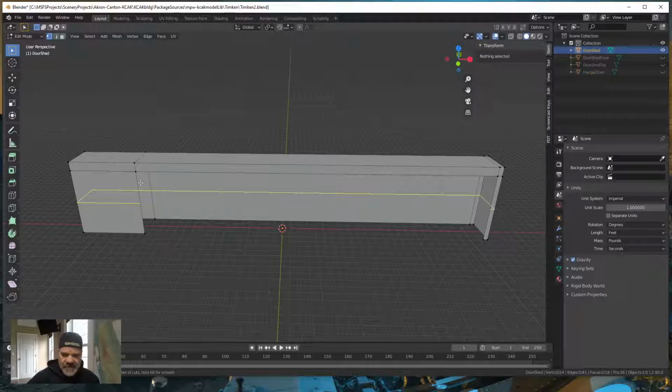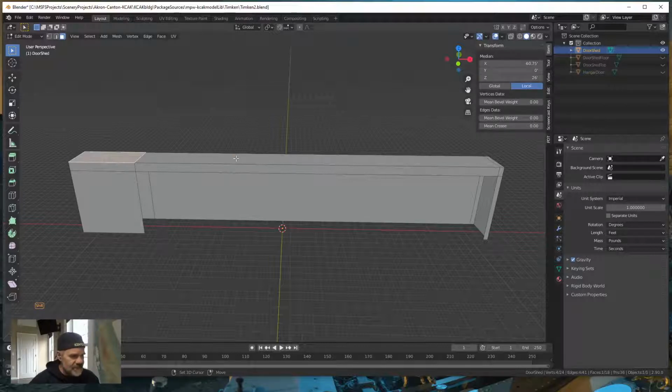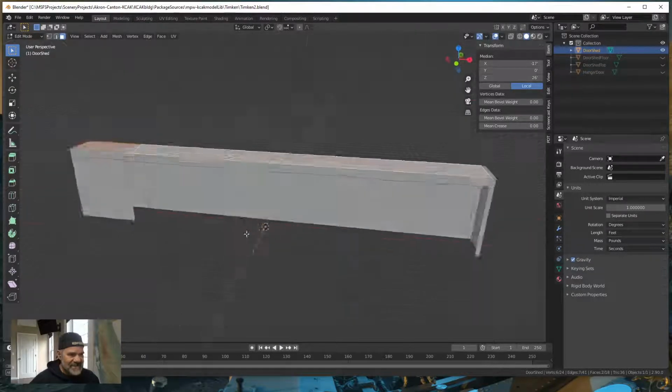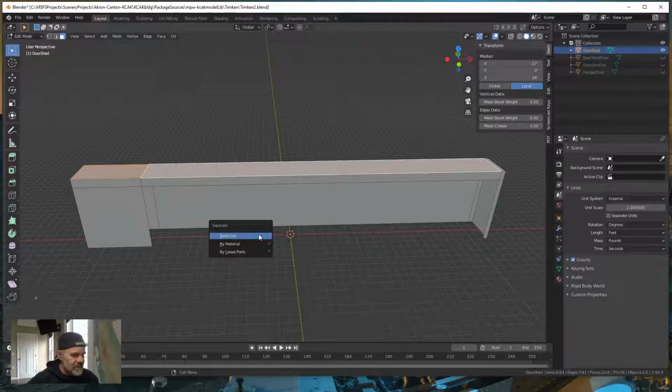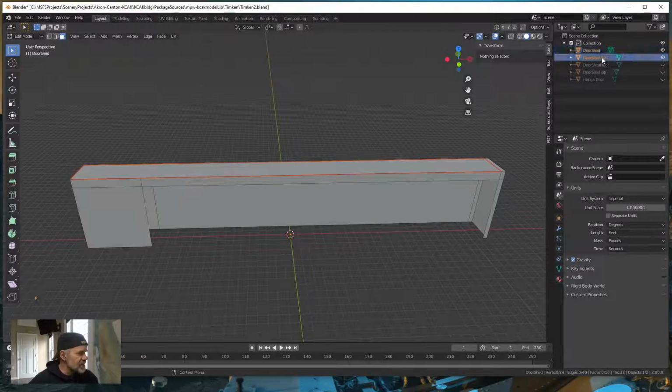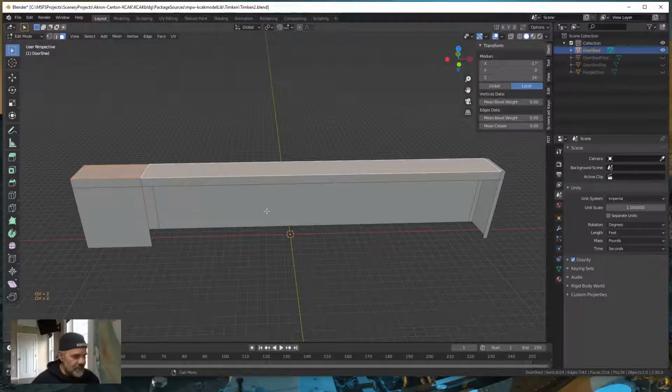So I'm going to hit escape to stop my loop cut, go into polygon select, and select what's kind of like a ceiling. I'm going to hit P to make a new selection. This is what I do, I don't delete it unless I'm really sure. Whoops, I forgot a polygon here, so I want to Control Z, Control Z, Control Z. So I undid what I just did.